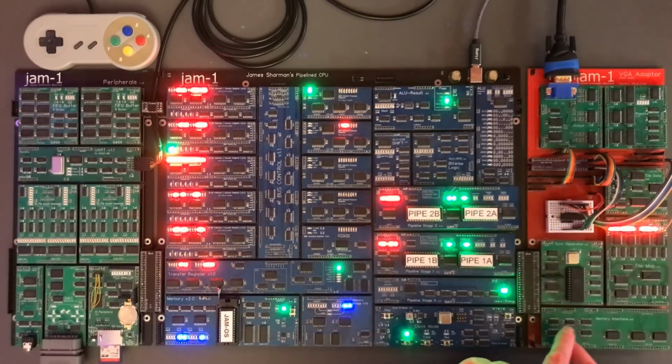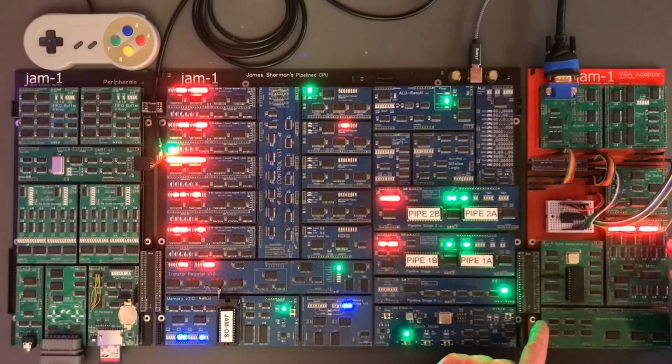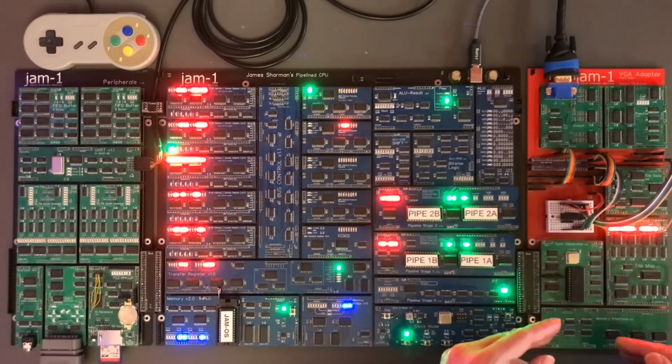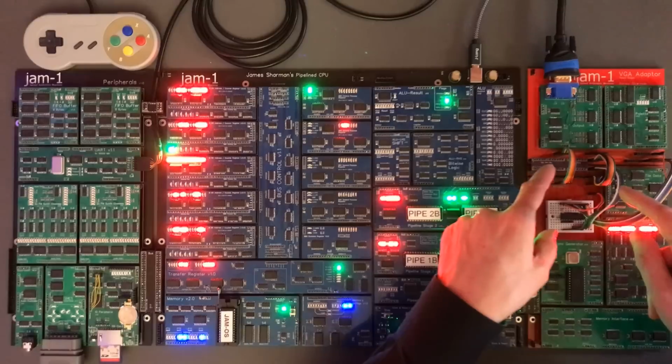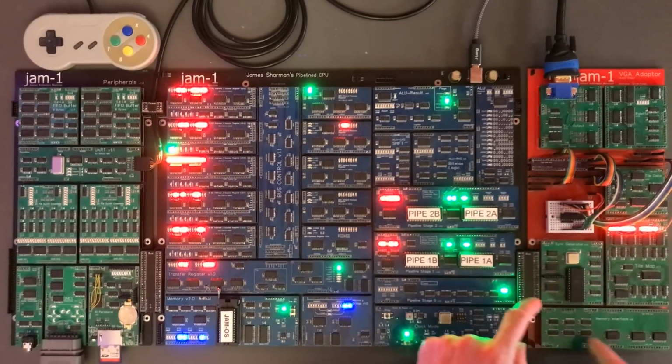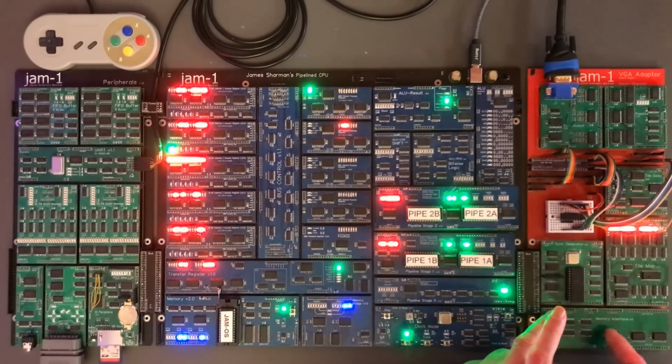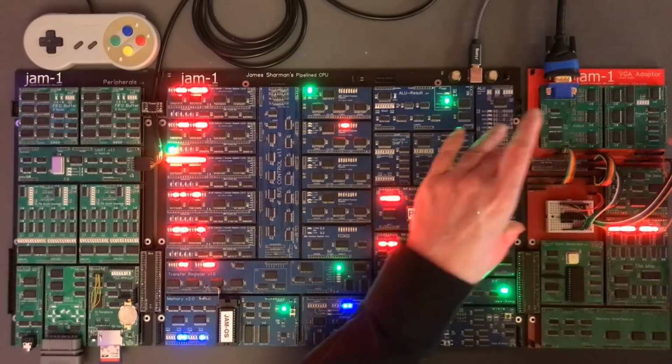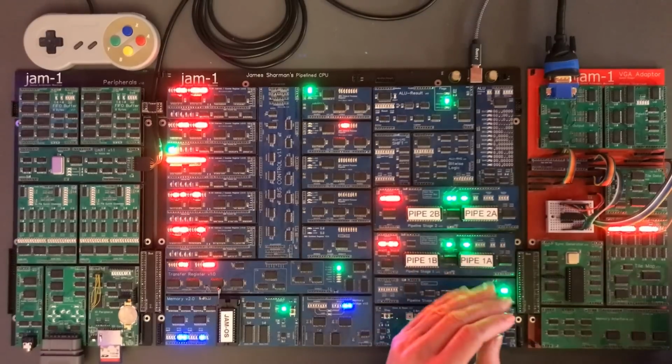The memory interface contains the driver logic for the registers. So there's direct load lines for these scroll-based registers in the tile map. And I did have a thought that some of the sprite registers were going to be locally controlled rather than controlled through here. But actually, if I just add the functionality for those registers to the memory interface, then it's going to be an awful lot easier to fit the additional componentry in there. It's more efficient for space.